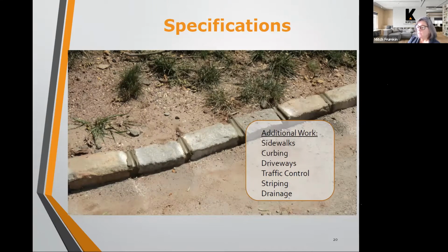That could consist of perhaps adding catch basins. It could consist of putting in perforated underdrains where there may be seepage conditions from the underlying soils. There are different types of drainage techniques, drainage improvements, that we can implement to alleviate drainage problems within roadways.